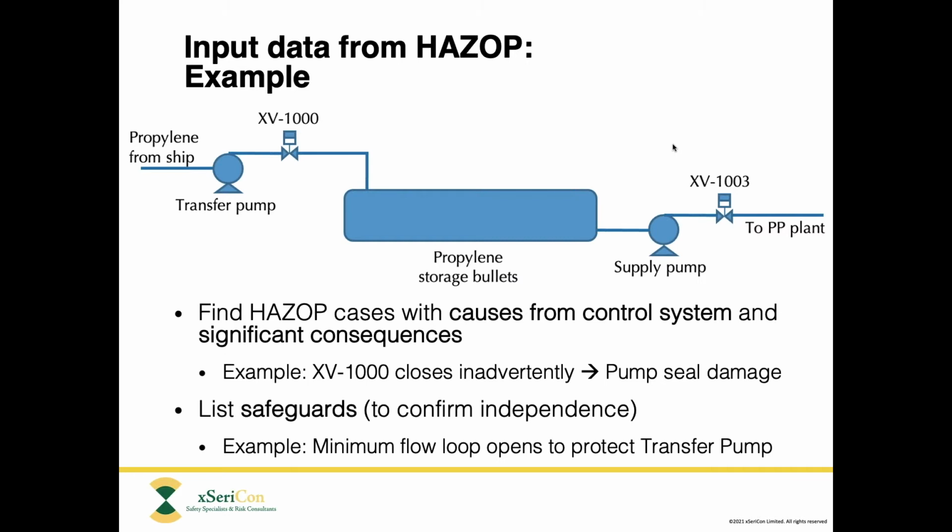three things really. One is the root cause, potentially like a fail high case or a fail low case? So for example, inadvertently closing a shutdown valve would be a fail low case, because usually a shutdown valve, you normally send it a logic 0 signal, or basically no signal, in order to command it to close. So that would be what we would call a fail low case.